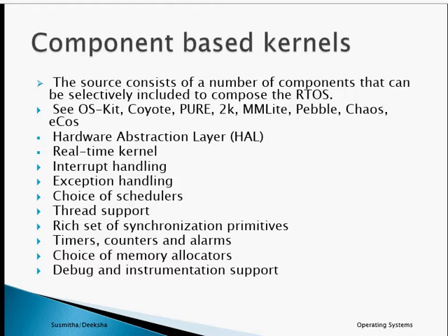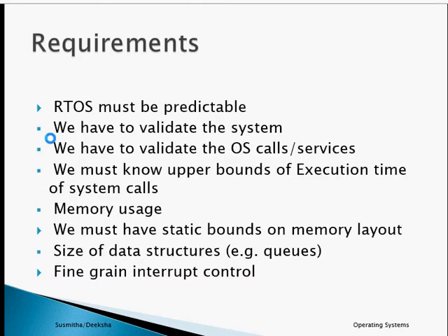Let's see the requirements of RTOS. RTOS must be predictable. We have to validate the system. We have to validate the operating system calls and services. We must know upper bounds of execution time of system calls.